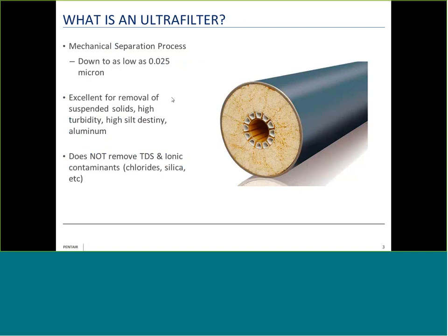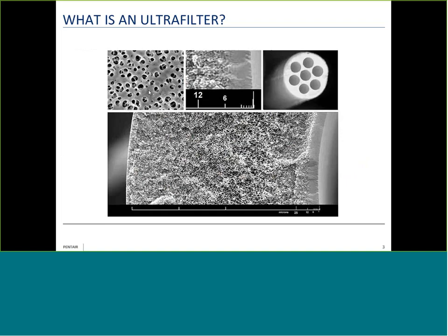How this works, you can see the raw water flows in. The debris is trapped on the inner skin separation layer with the smallest openings. They're preventing debris from being trapped or lodged deep in the capillary walls of this tube. These are capped at the end, but when it comes time to backwash the filter, it's going to open this up and allow it to flush through. And that's one of the nice qualities of a UF filter, that it's self-flushing, able to prolong the life of it.